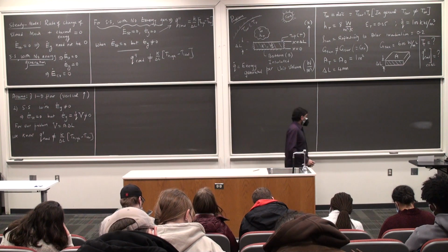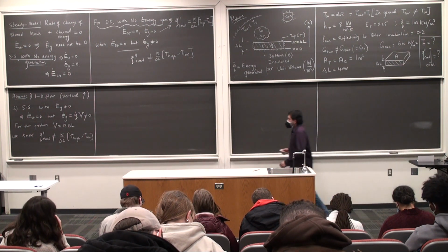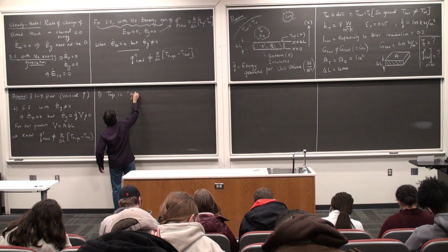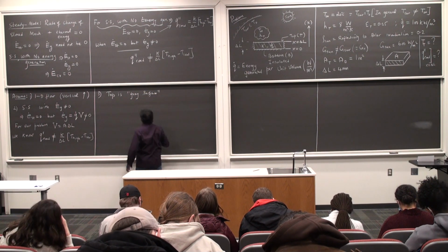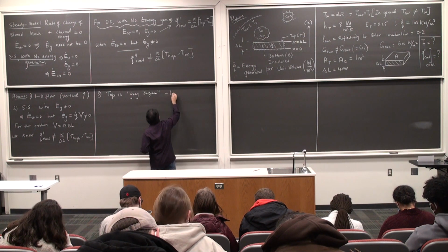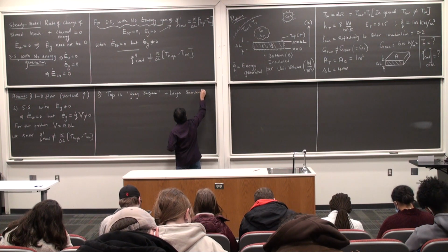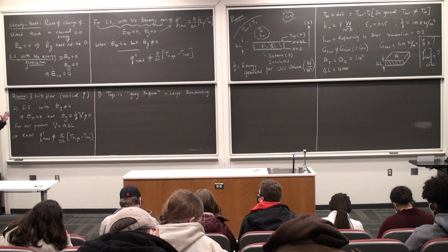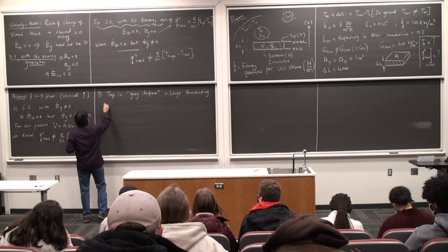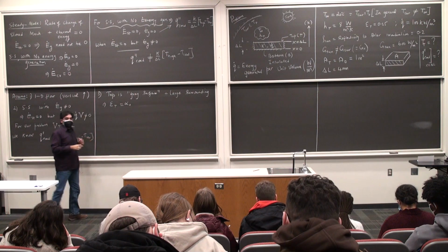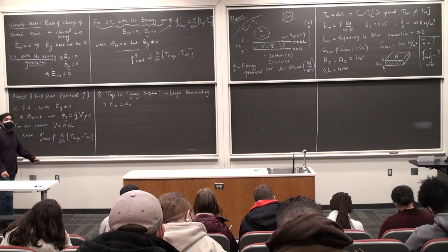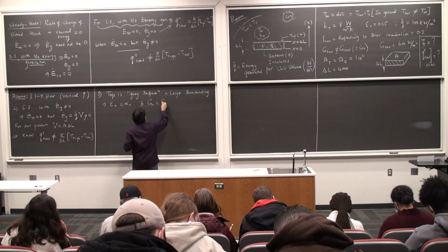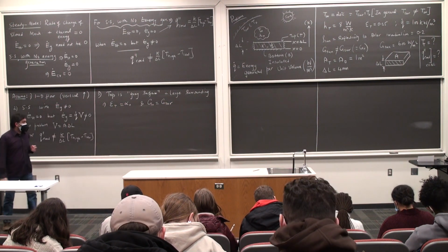A couple more assumptions and then we are on our way. I'm going to assume that the top surface is gray. And the surroundings are very large. Which tells me that the emissivity of the top surface is the same as its absorptivity to surrounding irradiation. Alpha naught, which I'm going to call the absorptivity to the surrounding irradiation. And G naught, which I had written as G surrounding previously, just not to confuse with the sun, because I'm going to write G sun as well very soon.